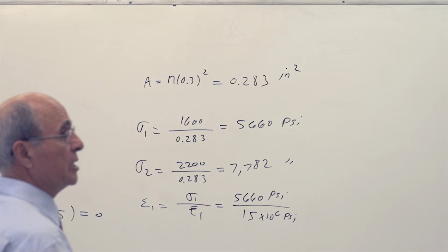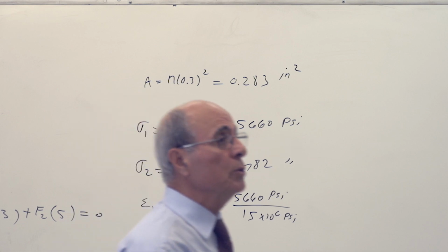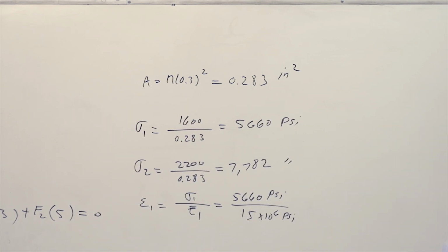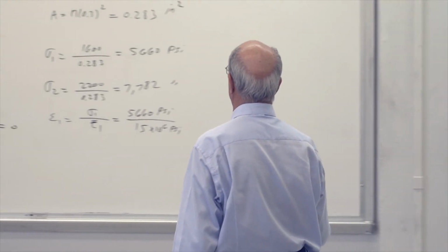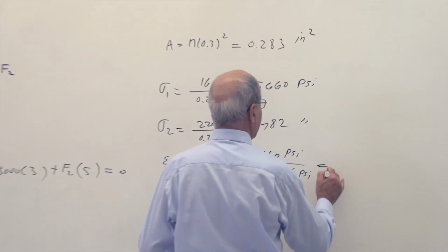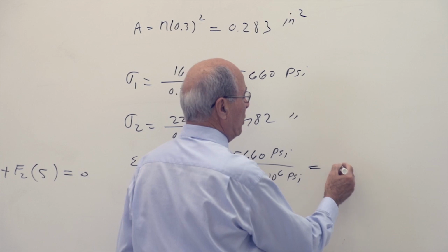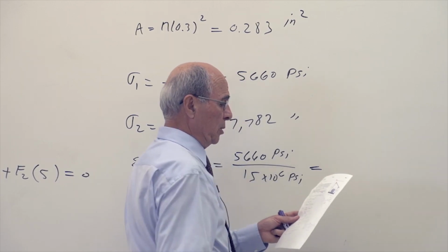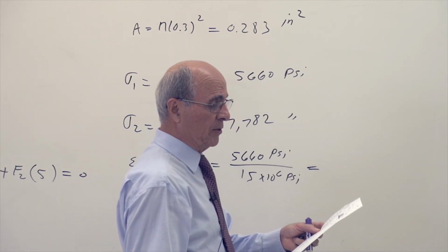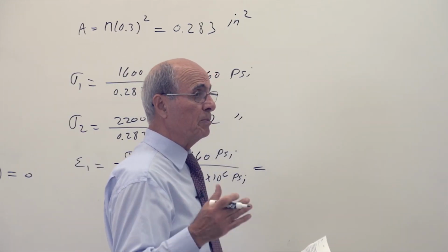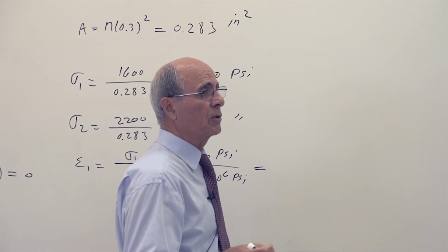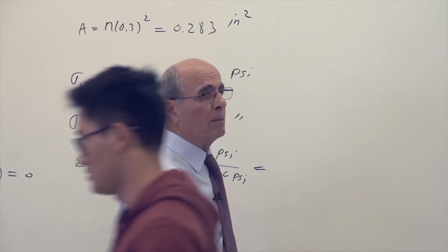Epsilon is the ratio, the amount of deformation per unit of length. So it's length over length. Everybody understand that. It's inch over inch. So therefore, this drops out anyhow. And then many of you come up with 0.00 or you use 10 to the power of -4, -5. This I said do not use that. Actually, the unit of epsilon, I mentioned it in class, is micro. Micro is 10 to the power of -6.